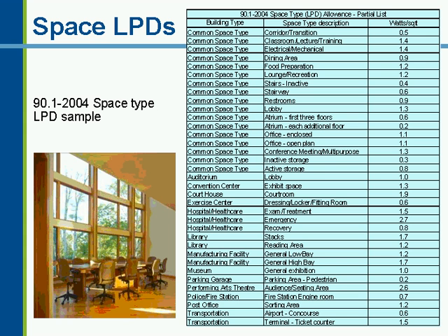Wanted to show you what some of the lighting power density values look like. This is a portion of the table. The table includes approximately 120 different space type LPDs. This is just one part of that table. One thing to note here is you'll see there are a lot of what are called common space types. These are space types you find in lots of buildings, and they're similarly lighted, and so they have one watts per square foot value, no matter what kind of building type it's in.